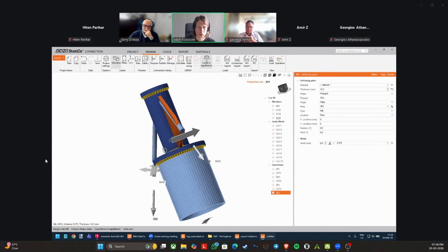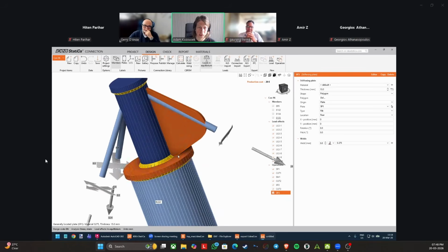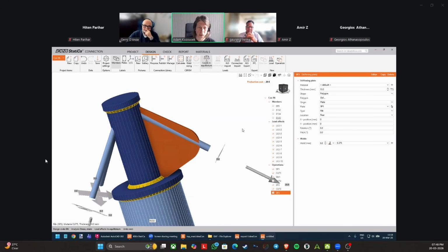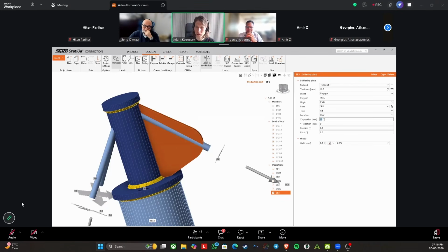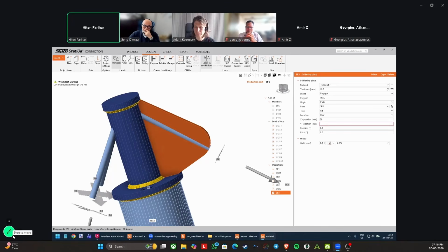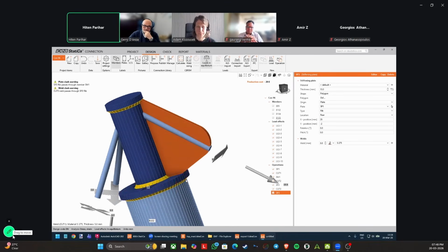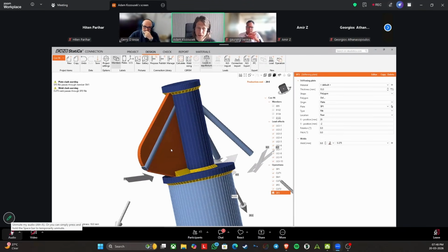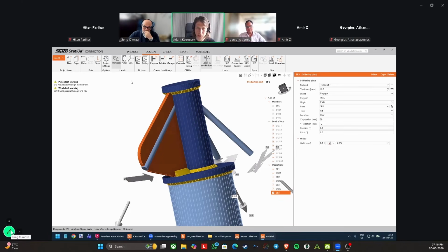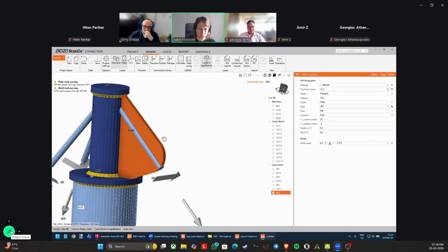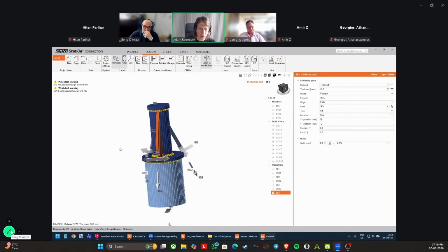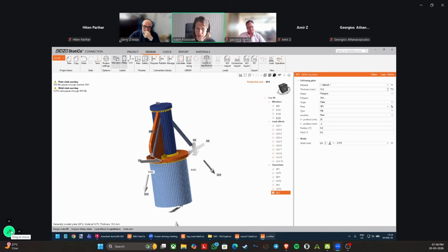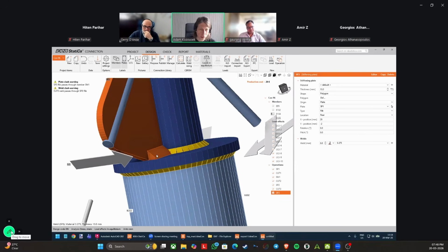So now this looks much better, right? And I need to move this plate a little bit outwards so I can move it with these X and Y coordinates. Exactly. And by placing this plate, which is SP3, right? This is the SP3 plate, and we placed it on a SP1 plate, which is this one. It also automatically creates the weld.